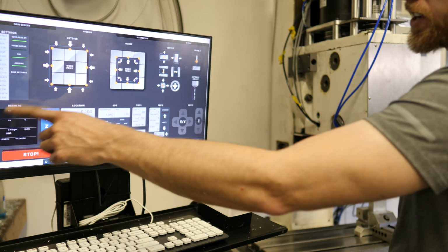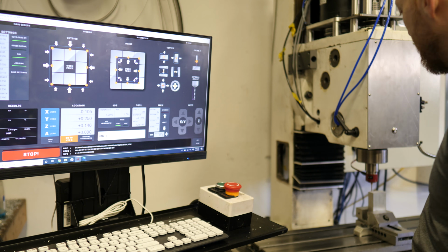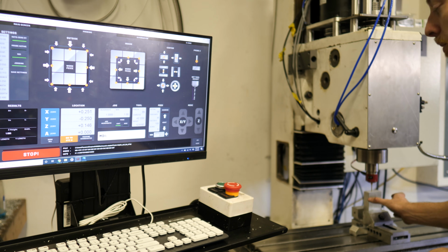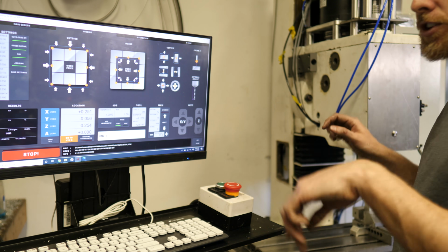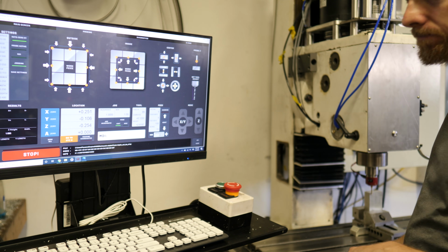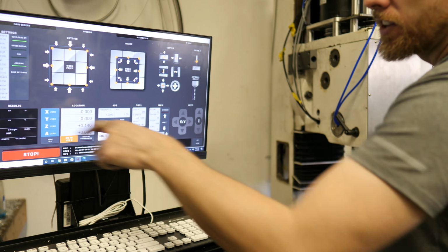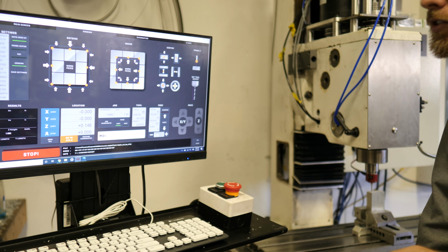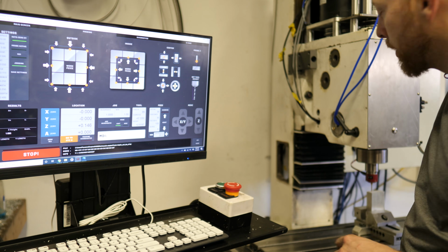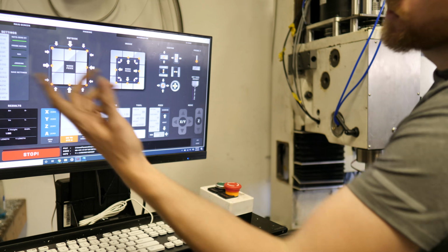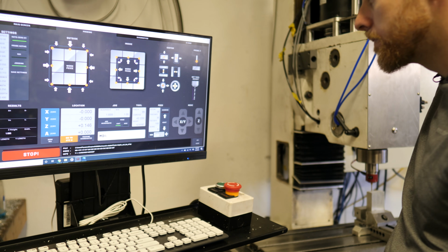This results page is actually super helpful for doing your calibration of your probe tip as well. Like, I put a workpiece in here of an exact known dimension, in this case a 1, 2, 3 block, and I measured each side of the 1, 2, 3 block, and it'll tell me the X plus, X minus, and the delta between the two. So if it says exactly 3 inches, then I've got the probe tip right, and I calibrated it that way. You see here now we're within 1 thou. Pretty accurate enough for the stuff that I do.